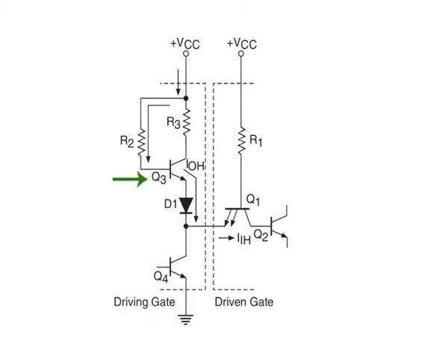Transistors Q3 and Q4 constitute what is known as a totem pole output arrangement. In such an arrangement, either Q3 or Q4 conducts at a time depending upon the logic status of the inputs. The totem pole arrangement at the output has certain distinct advantages.